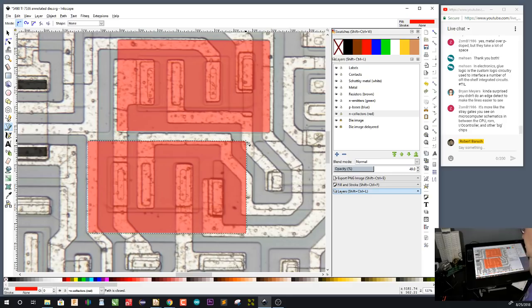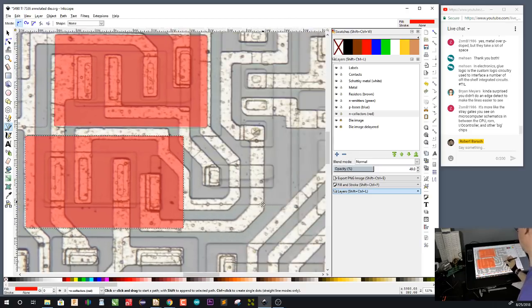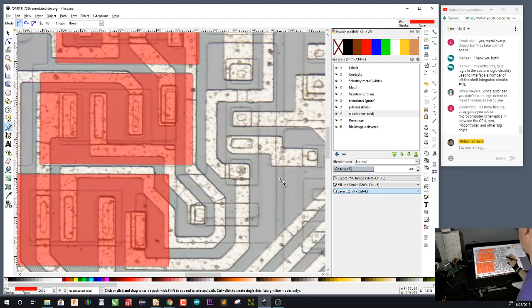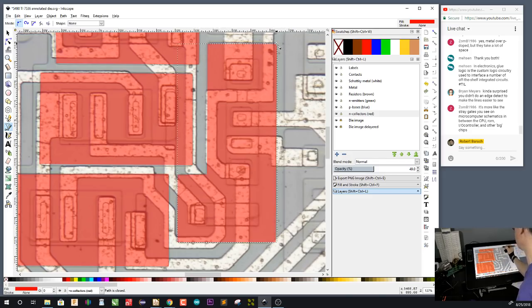It's not an ALS, A stands for advanced, or anything else. This is what they call a standard technology chip. And the standard technology chips are the easiest because the transistors are the largest. There aren't a whole lot of extra components and extra connections going all over the place for optimization for low power, optimization for speed.